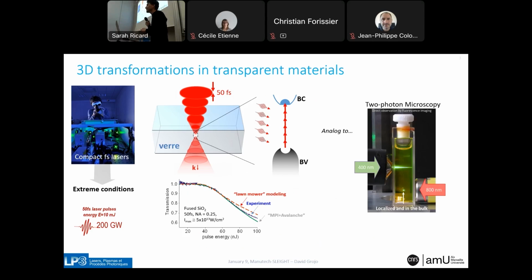So this is very analogous to what you have seen in microscopy studies. When people talk about nonlinear microscopy or two-photon absorption microscopy, when you work with a short wavelength where you have a 1 photon response, of course you excite the material all along the beam path. But as soon as you work with a wavelength long enough so that the only way you can excite is by multiphoton processes, you can localize the excitation or the energy deposition. So it's very analogous, with the difference that in laser processing, most of the time, we will rely on extremely high order multiphoton absorption responses.